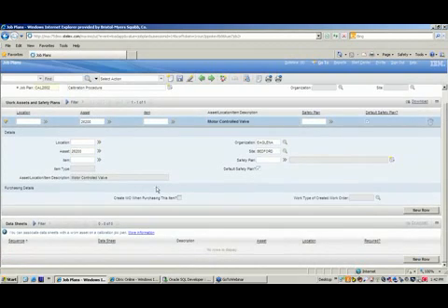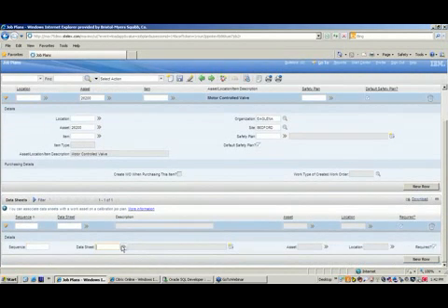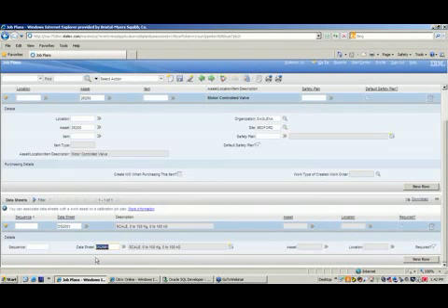Then in our lower section under the data sheet, with this record selected, when we select a new row and we look for this data sheet, we're looking for a value that's already been approved for this process. Currently we show 3 data sheets that are tied in. You bring in the data sheet that this job plan will be used when this asset is called in a work order. The data sheet here now is associated and will automatically be copied right into the work order itself.